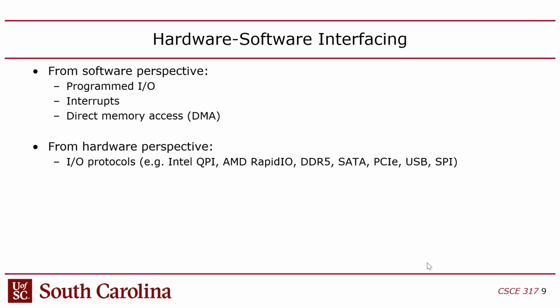Like, they could be outside the CPU but still within the chip, like in the case of a system on chip design, or they could actually travel outside the CPU. Like you could do a programmed I/O and it'll literally come outside the Intel CPU across the QuickPath Interconnect all the way across the PCI bus and down to your network adapter with one store instruction, right? That's possible, right? So you might say, well, then why haven't we ever done that before?